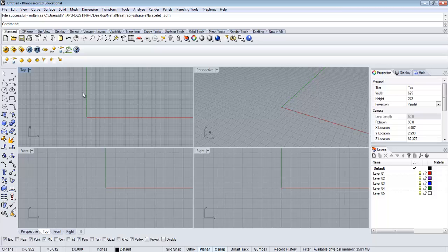When you're going through and developing something for 3D print, the really important principal thing is to think of a water balloon or a watertight object. Why think of a water balloon? Well, when you have a water balloon, you have a very distinct interior and a distinct exterior. The water's on the inside, and you have a thin membrane that surrounds that.